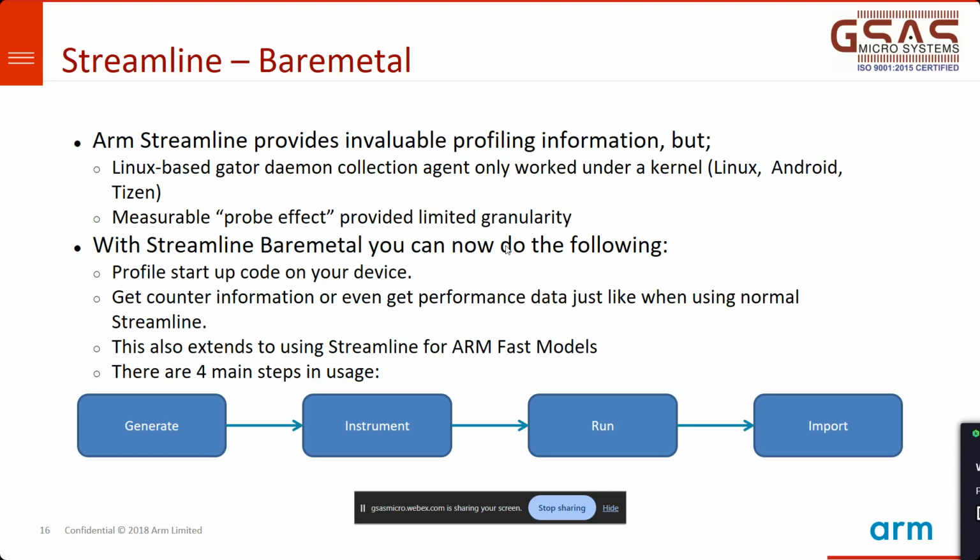So what will be such code? It can be startup code, because the ARM processor is a complicated processor, and whenever you give the power-on reset to the processor, reset itself is the highest priority exception. So that has to be serviced first, even before the processor hits your CMain function. This reset exception handler is defined in your startup code. I'm just giving an example. If it is a higher-end Cortex-A or Cortex-R, you may have to invalidate the cache, invalidate the TLBs, and do MMU initialization, TLB initialization, cache initialization. Everything is done in your startup code.